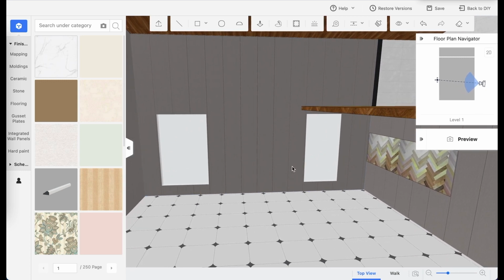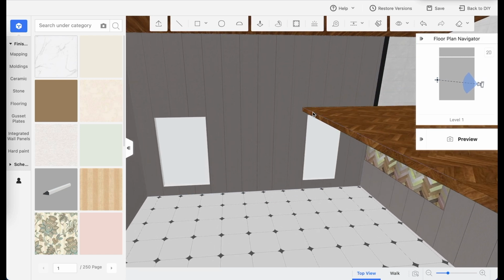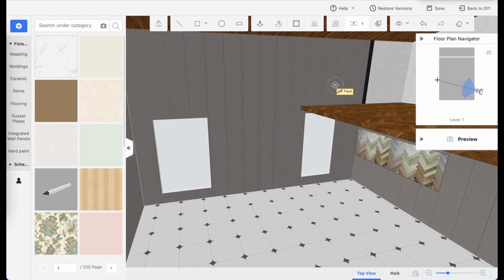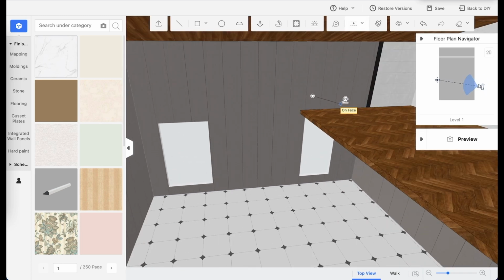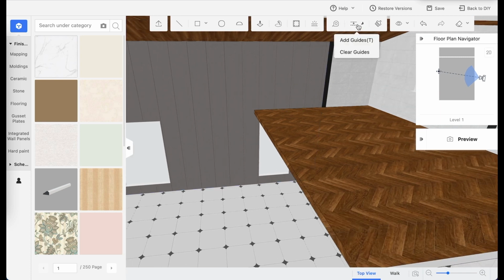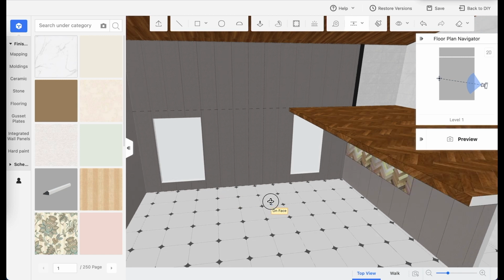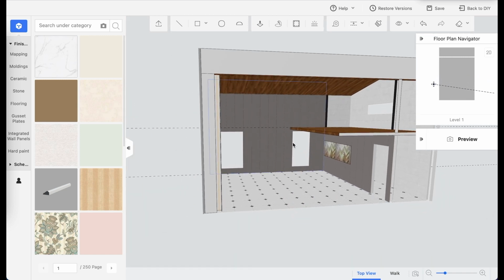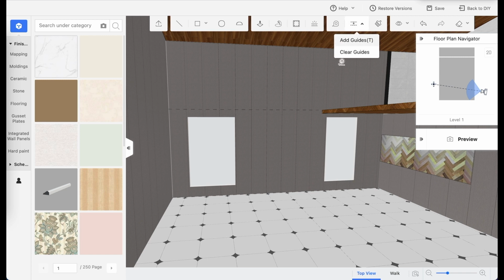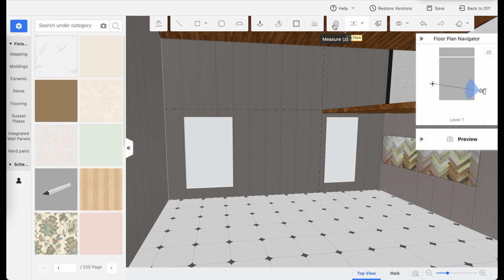The first thing we need to do is draw a stair coming from the level below to the second level. You will need to calculate the height difference to the top of the floor on the second floor. Your first reaction would be to use a guide here, which was my first instinct too. But soon enough, you'll realize if you use a guide here, and create another guide with the lines snapped to the bottom of the floor, it's really hard to get an accurate measurement of how far your upper-level mezzanine actually is.